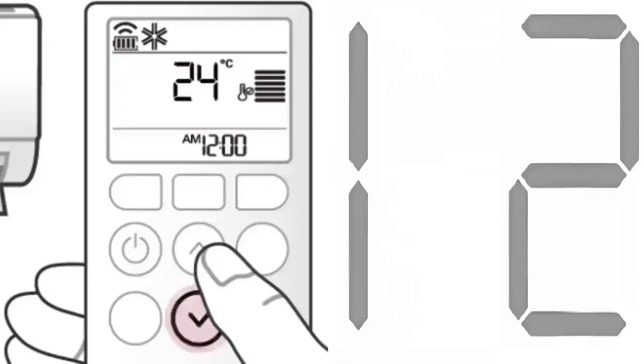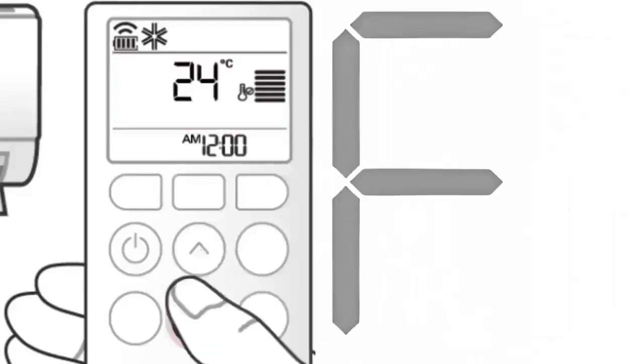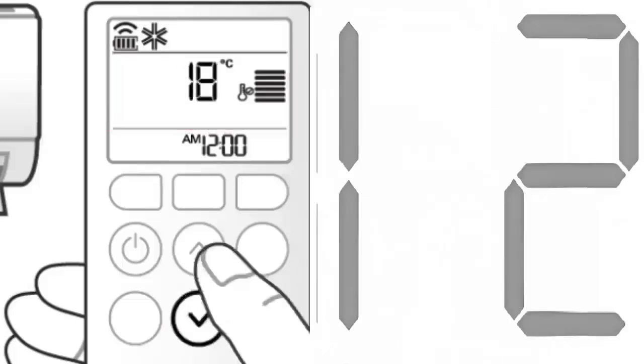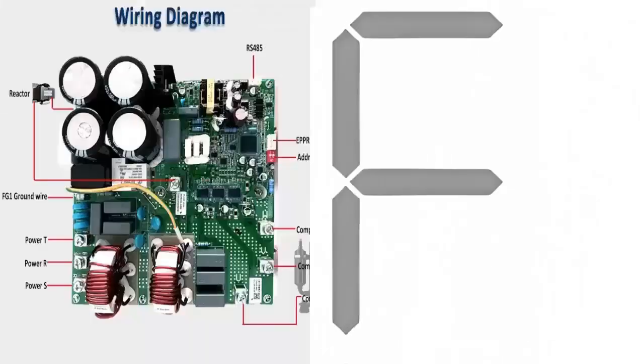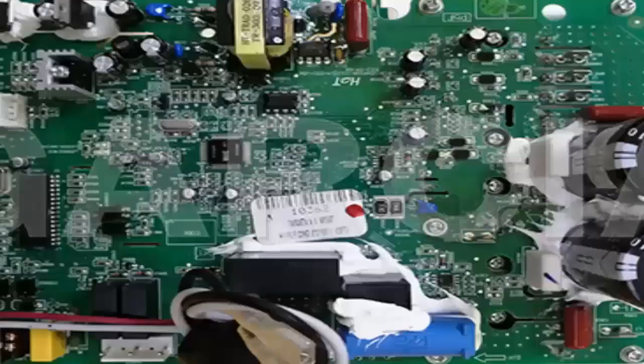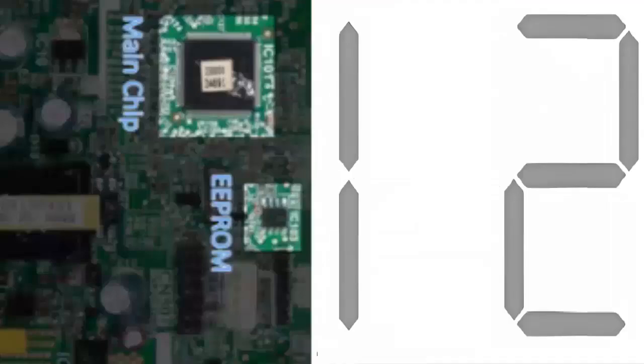2. Reconnect the unit and turn it on. 3. Observe if the F12 error appears immediately. In many brands, when the problem is specifically with the EEPROM memory, the unit might change the value or number of the error code several times.